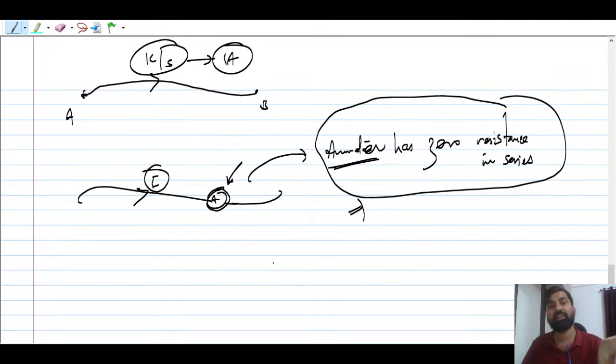In case of a voltmeter, we will apply the voltmeter across a certain element, right? So we have to make sure that the resistance is infinite or very high, so that it should not disturb the entire circuit, okay, understood? This is very important.